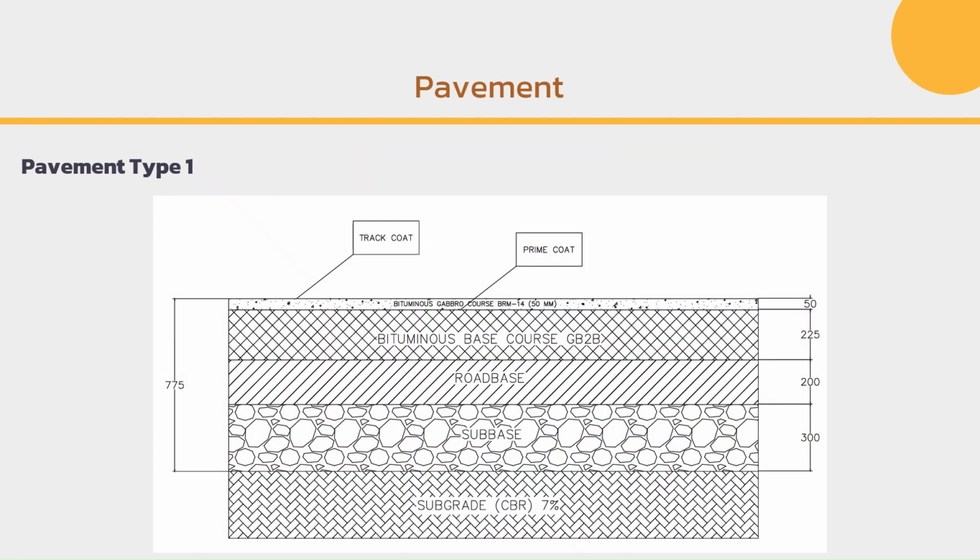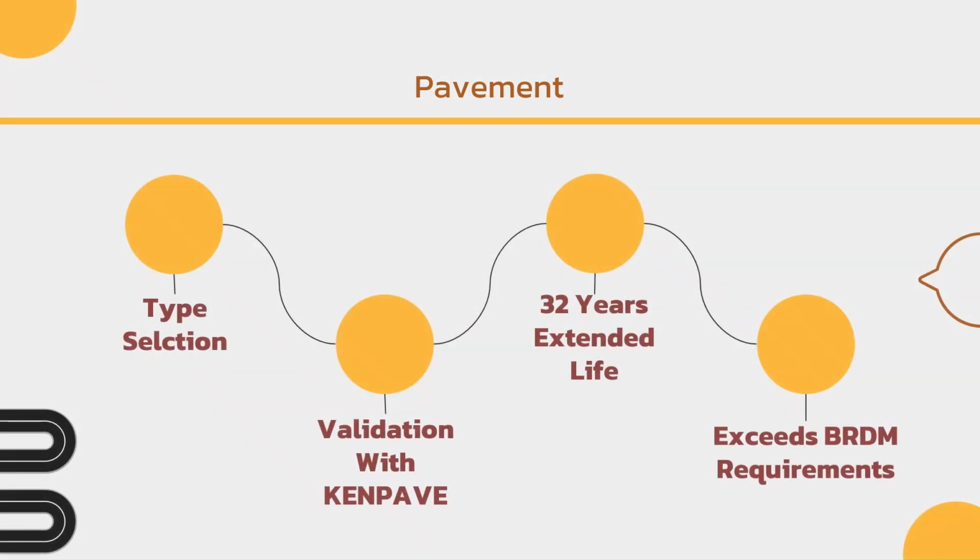For the pavement, we have chosen type 1 pavement from BRDM options, and we have run the design using KENPAVE. We achieved 32 life years, which exceeds the BRDM requirement.